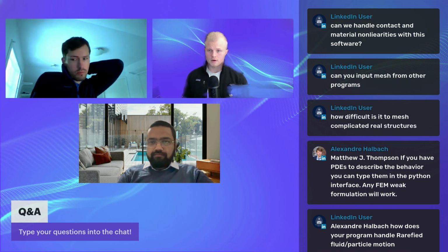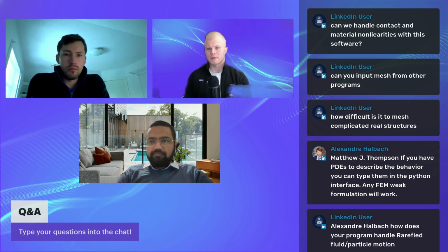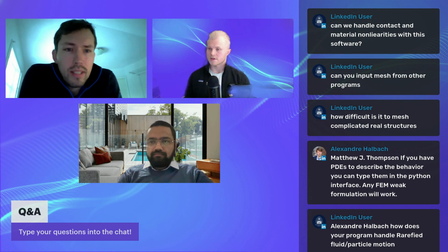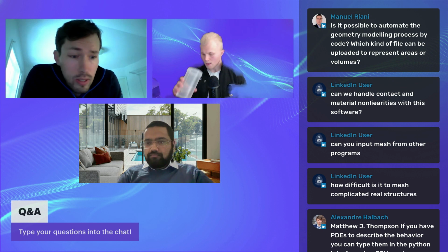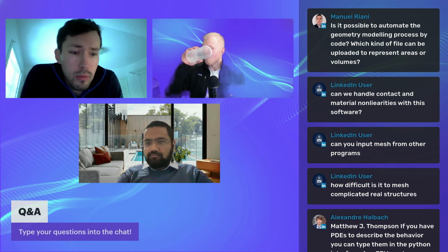All right. Then answer question on material nonlinearity. Can we handle contact and material nonlinearities with Quanscient also? Contact, yes, we even made some LinkedIn posts regarding contact using the mortar finite element method. We have even done CMUT ultrasound membranes with electrostatic force in contacts, also including mesh layers between the two contacting pairs. We've done pretty nice things regarding this.